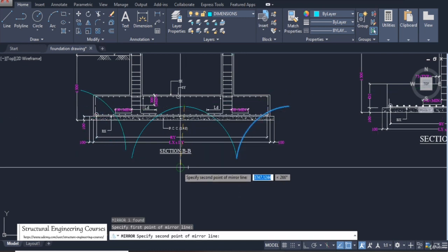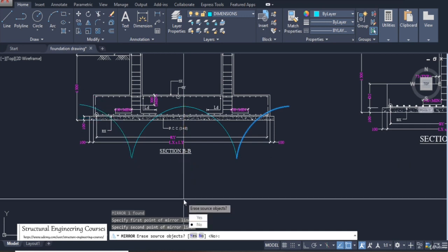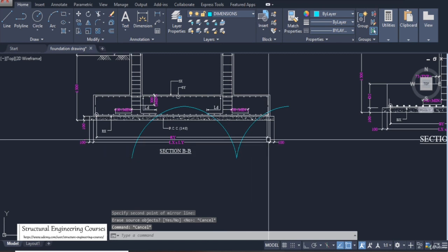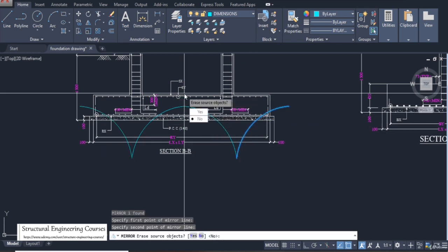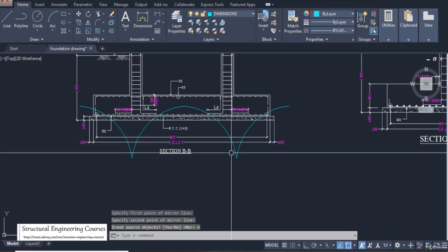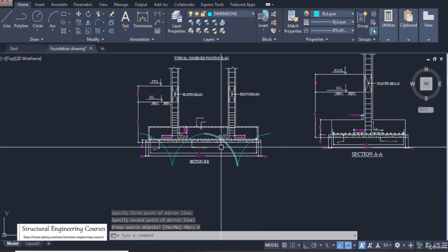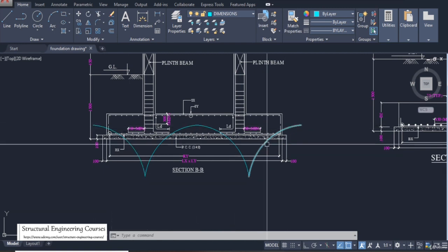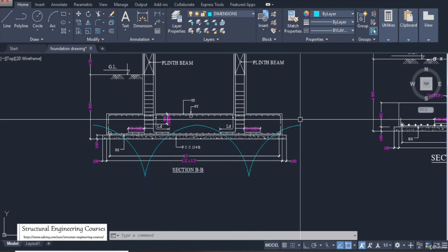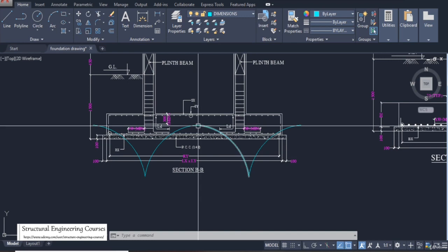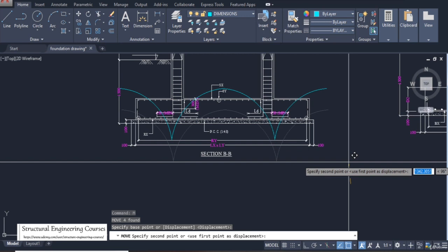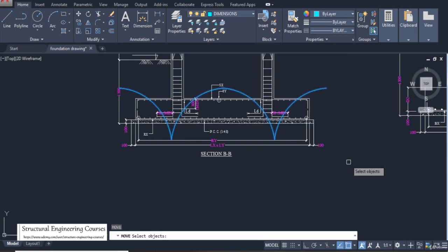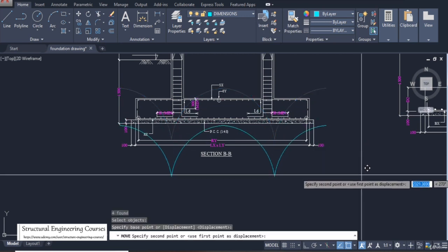Always, as a doctor, you should understand that a good doctor shall always understand about the body parts. Similarly, as a good structural engineer, you should understand how the bending moment and shear force may flow in your structure. So this is just a rough bending moment profile. This is WL square by 2, and this moment is WL square by 10, and in some cases it may go on the top, and in some cases it may remain on the bottom only.